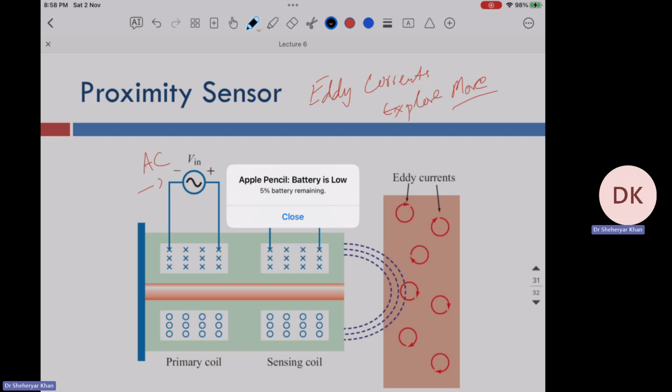Because when we use a motor, it produces a magnetic field by induction, but it also has currents. That current passes through the material of the rotor, and then that current will have high I squared R losses, and we have to pay for it. In a motor, we actually don't want any current. So what we do is